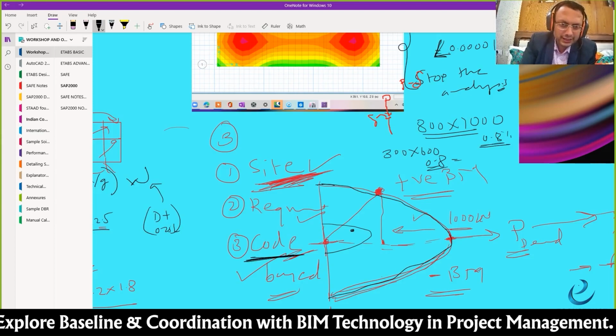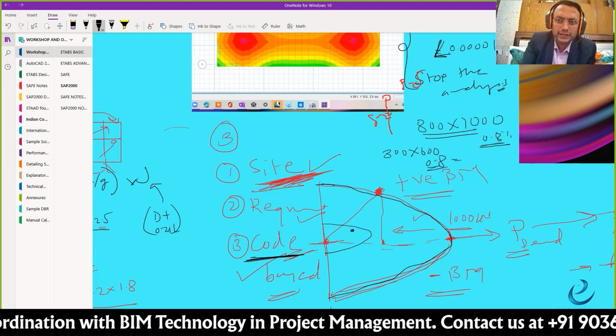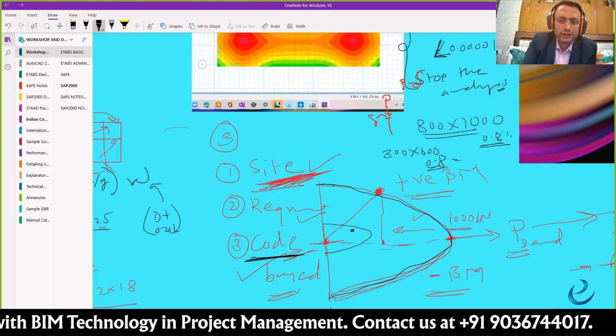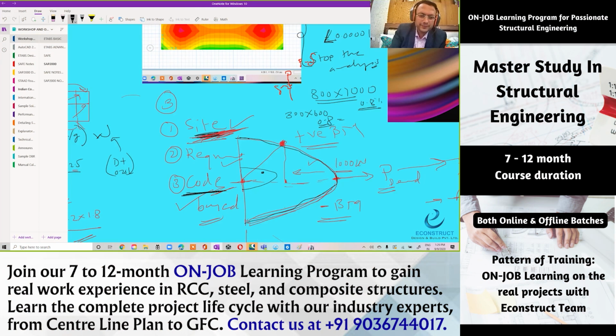So these are the pressures on the structural engineer's mind, and based on that he needs to take a call on what reinforcement to give. Just a few minutes back, Mr. Tushar said you require the 20 mm bar at the lower level even if it is not required, because on the top floor you require 25 mm. As a site engineer you cannot take that call, but since you know these design aspects, you can take this sensible call right away. Understood?